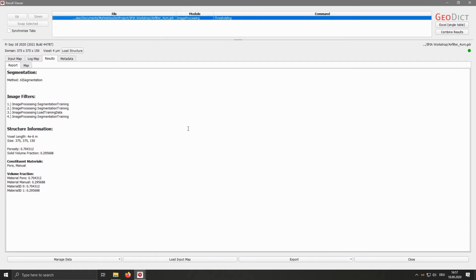And the 2D one performs pretty well. It is by default looking at Z slices, but you can switch this around in the options. And they profit from labels being close to each other. So if you label an area, then put in as many labels as close to each other as possible to get a fully filled output window. So now for me, the segmentation with the boosted tree method is already done.